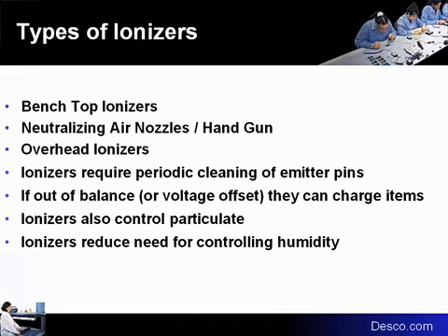Overhead ionizers are used for some of the larger bench areas. These all today have auto balance systems that monitor themselves and will alarm, but they do all require maintenance in cleaning emitter points and monitoring controls.